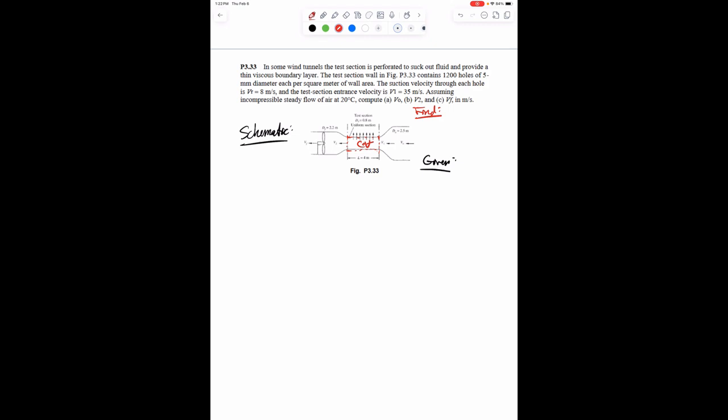So this control volume, I can then use Reynolds transport theorem, and considering the fact that I'm interested in finding properties such as velocities, and I'm given cross-section area and those kind of terms, it's most likely that we're going to be using the mass conservation equation in order to get our values, because we just want to solve for velocity. We're not trying to solve for force or anything like that.